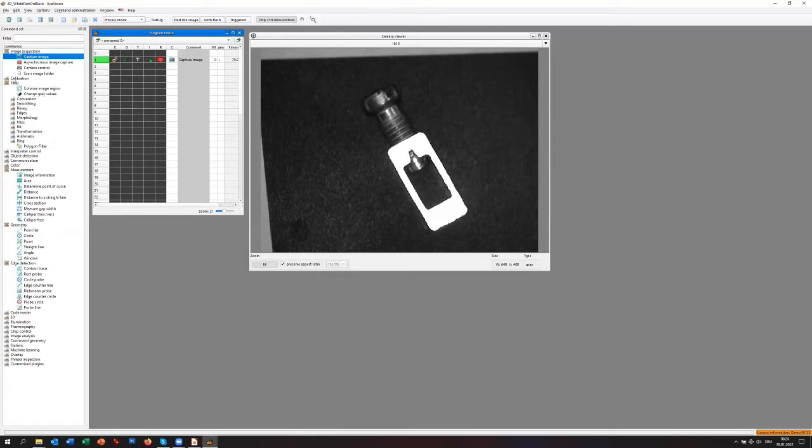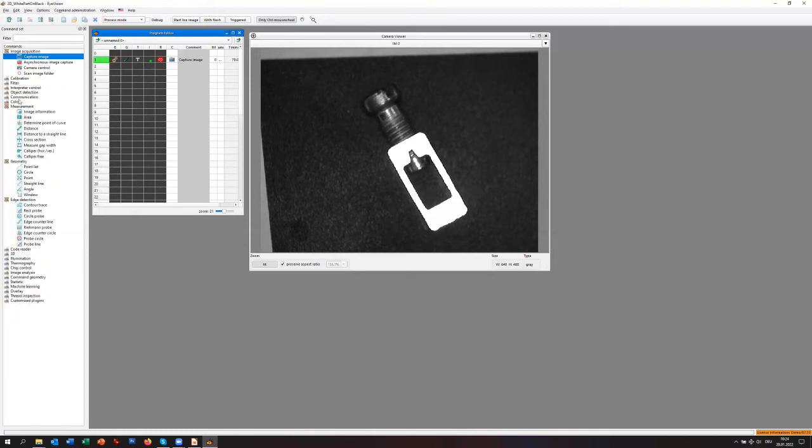We have all these filters in the software, as is normal, but on the other hand, you should also take care, as I mentioned, the edge is the basis of an accurate, perfect measurement. If you have a bad edge, the measurement is not good, or a bad measurement, however you want to name it. That's why I really recommend, first of all, to adjust the light and lens situation to get the right solution.